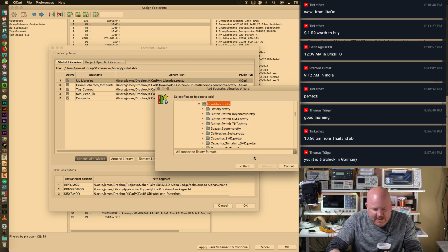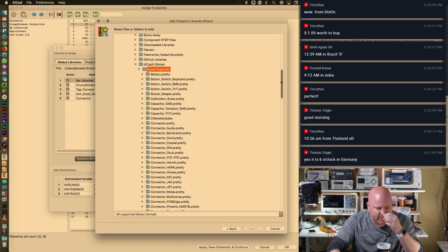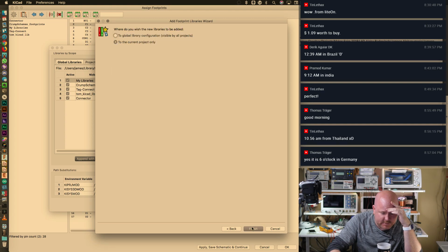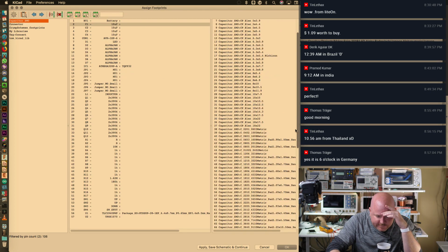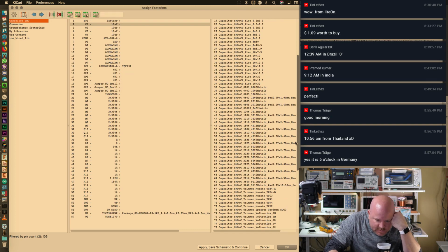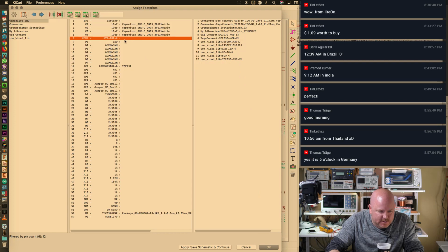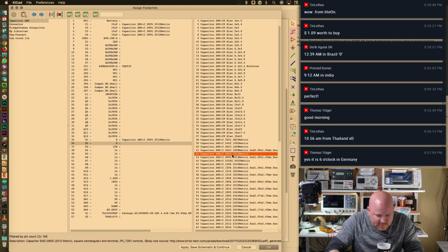In my setup, I've actually removed all of the footprints because there was a bug early on with the capacitor footprint that was giving me problems, so I just said to heck with it. I just need an 805. That's for hand soldering, and I'm not doing hand soldering. So 10, 10, 10. The LED will be a 1206. These are for capacitors, but for resistors close enough. These are all 805.